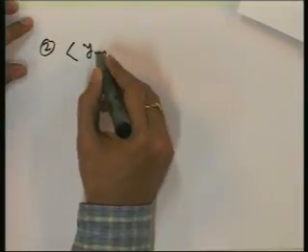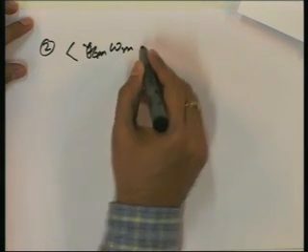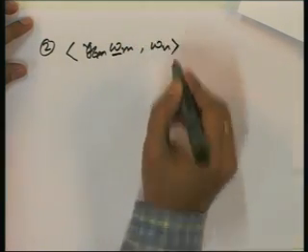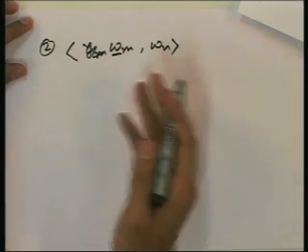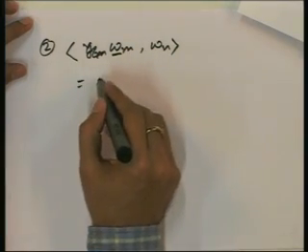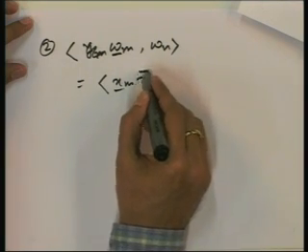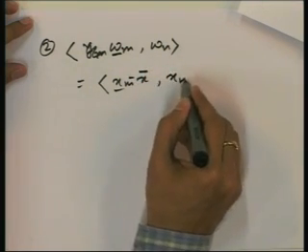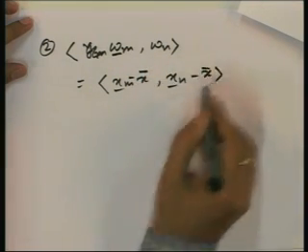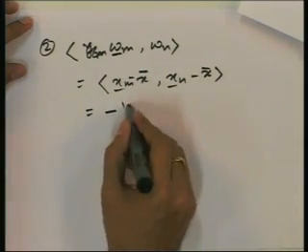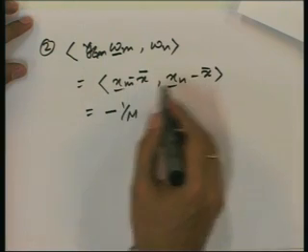Now, second, what is the inner product of xm and xn, two signals in the simplex signal set? For the orthogonal signal set it was 0, but now they will not be orthogonal, and we can compute this. Once you compute, you will see that this is minus 1 by m, and it is independent of m and n.